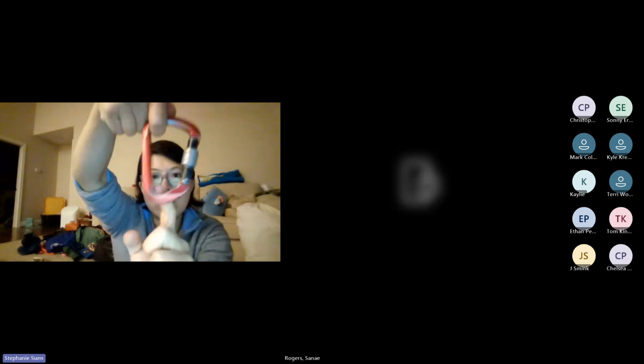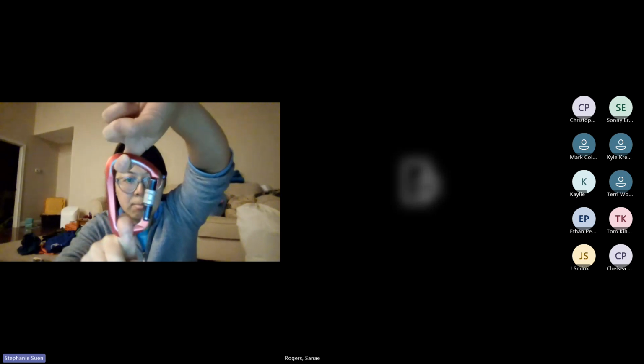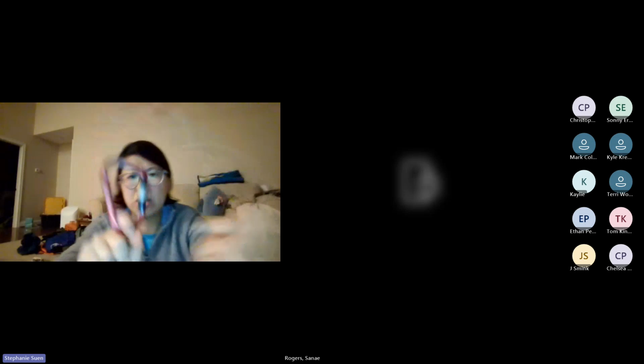And generally we consider D carabiners, this is a D shape carabiner, to be one of the strongest shapes, because my rope is going to naturally want to sit at these points here. You can look at the wear on this red carabiner, where it's worn off the ink. Naturally your rope wants to sit here and here, right? So if you had knots on this, or it was sitting in an anchor, that's naturally where everything wants to sit. Everything naturally sits with all of the strength along the spine on a D carabiner, and that's its strongest position.